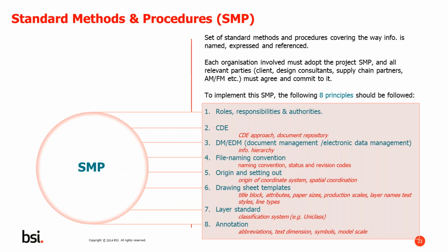So the standards, methods and procedures that it defines cover the way the information is named, expressed and referenced. So each organization involved must adopt the project SMP, standard method and procedures, and all relevant parties, clients, design consultants, supply chain partners, asset managers, facilities managers, they must all agree and commit to using it. And in order to implement the SMP, the following 8 principles should be followed.